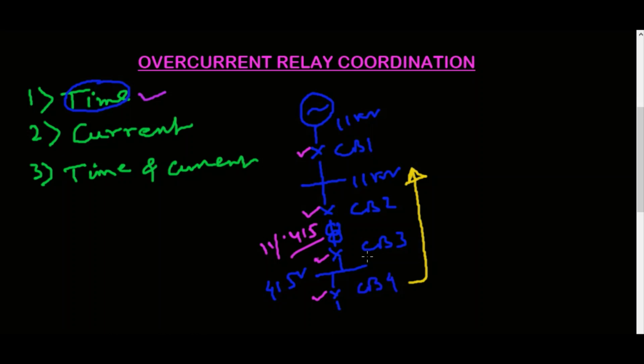With the ETU trip release, a separate relay is not required. But for this medium voltage or high voltage network, we need to consider relays, and for that this is the CT. With this we need to consider a relay here. Suppose this is relay 1, here is another relay, suppose this is relay 2, this is R2. That means we need to coordinate with the downstream LV circuit breaker with this relay R2, and along with that we need to coordinate this R1 relay as well.